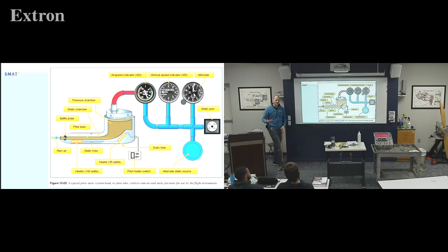Now the cockpit's going to be just ever so slightly different pressure than outside the aircraft. If I was teaching you guys as pilots, I would memorize if it's higher or lower. I used to know this. It's higher or lower, because if I switch my alternate static, my airspeed would actually change a little bit. You can do that research on your own. Point being, it's a little bit different pressure inside the aircraft than outside. So normally we leave that closed and we sense outside the aircraft. We are going to put that outside the aircraft pressure to our altimeter.